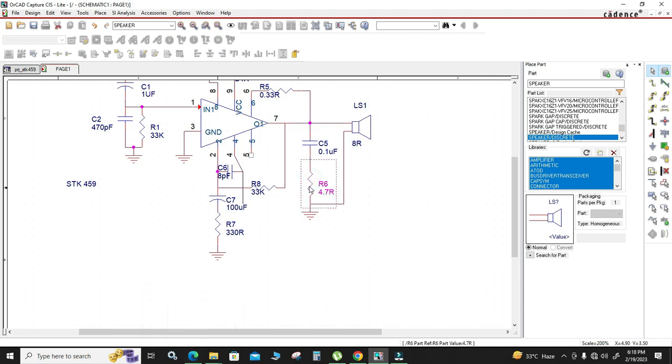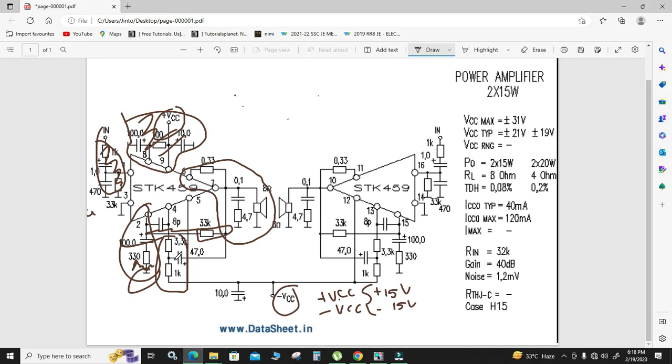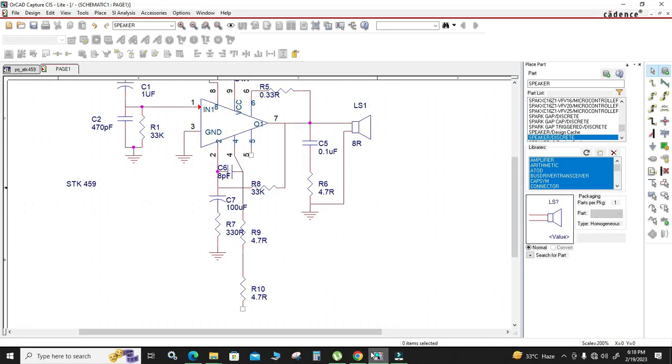Then choose a resistor division for 1 and 2. Then one here, then one here. Okay, so this midpoint is division 1. The midpoint is connected to a polarized capacitor and directly connected to the output. Polarized: the plus is on the other side, the minus is connected from this side. This plus side is the plus pin, which goes directly to the output pin.